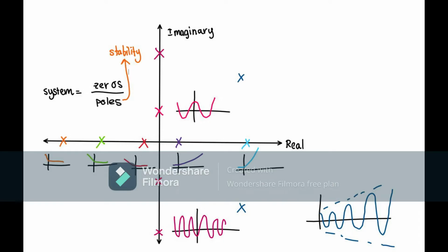Now that we know where the poles and zeros stand in the graph, let us draw this in the S-plane. The S-plane is drawn with imaginary components in the vertical axis and real components in the horizontal axis. Poles found in the negative plane of the real axis indicate that the signal of the system decays, and the further away from the origin, the faster it decays. On the other hand, positive values behave in the same manner, but represent an exponential growth of the signal.